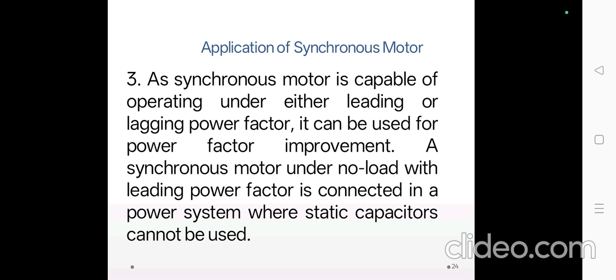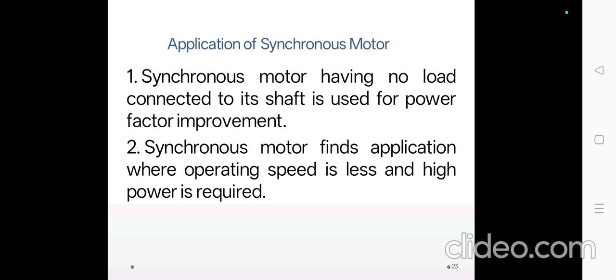Alternators and other equipment result in poor regulation. Next, there are many types of excitations in the synchronous motor. That is normal excitation, under excitation, over excitation, and critical excitation. First one is normal excitation. When the excitation is adjusted to get EB equal to V, that is, induced EMF is equal to the applied voltage, such an excitation is called normal excitation of the motor.